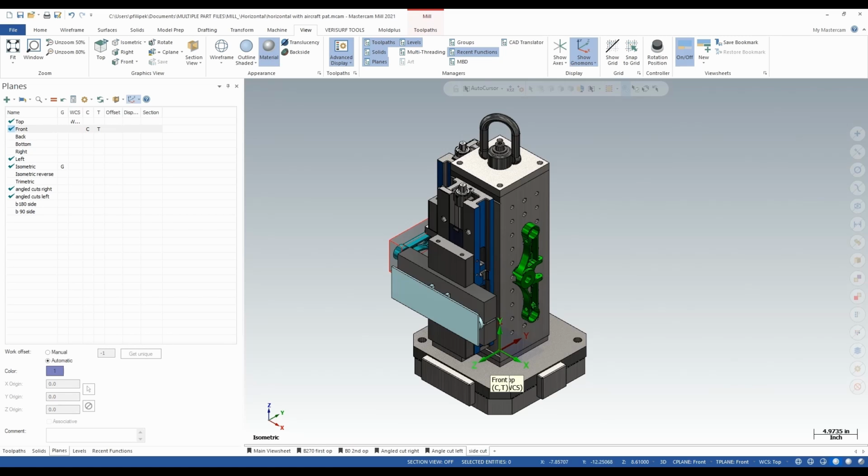and it builds a view sheet on the bottom. Now if I look down here, all the rest of the view sheets have these little symbols here. What that is, is a bookmark. So if you want your view to stay the way you made it, we need to right click on that view sheet that we just made, and we go to save view sheet bookmark. And in this right click, while we're here, there's a few other options: a new view sheet, a copy view sheet, rename view sheet, or save view sheet bookmark, which will lock this view in on this view sheet. So I'm going to left click on there and you'll see the symbol comes in there.